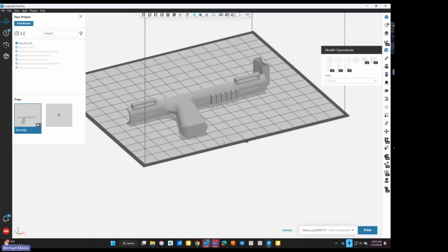Now that does take longer, but this also does another key component to the nylon, and that is actually to hydrate the nylon material, which gives it its durability and its flexibility. So if you are not tanking your nylon parts, I highly recommend to do that because that's where you really get your strength characteristics and your flexibility out of it.